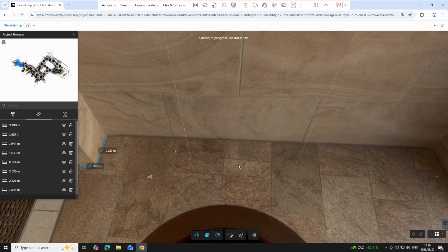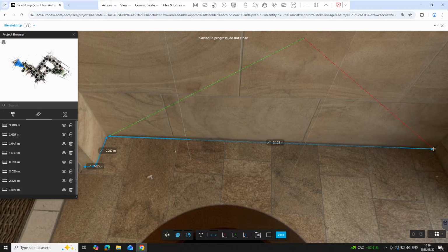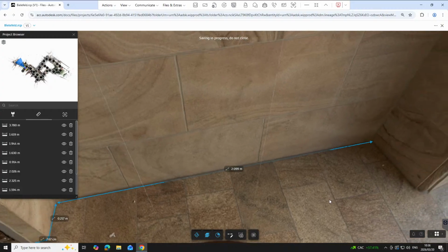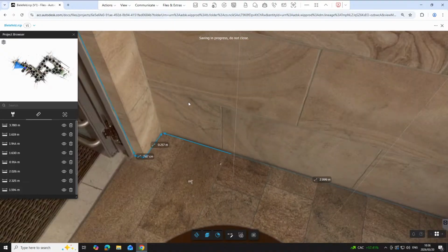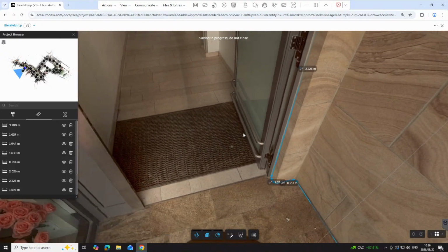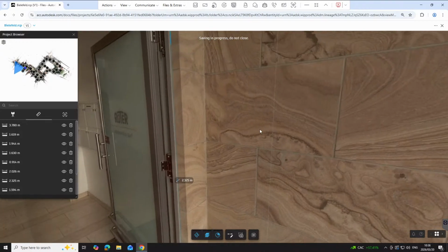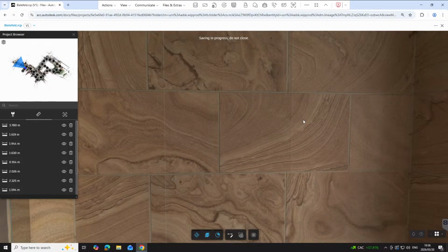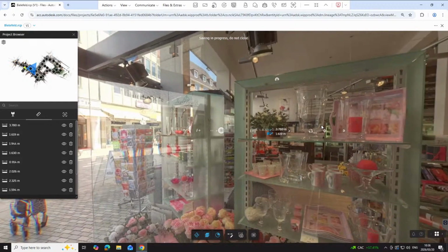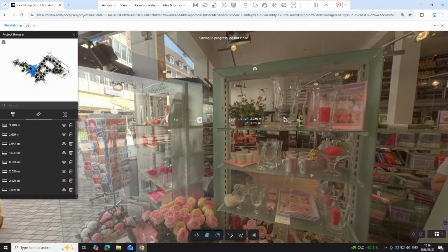And the idea is that you don't have to go on site with a measuring tape to grab the relevant information. And there are even better workflows than this, where we scan to mesh within Autodesk Recap itself, and we can actually pick out the individual items so that we can create a poly mesh, say, from the entire face of this wall, and so on and so forth. So this is the method of navigating your point clouds.